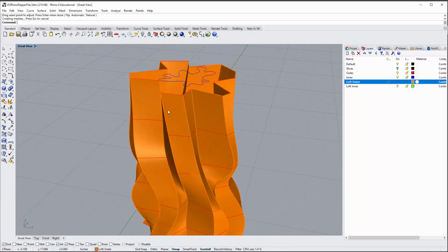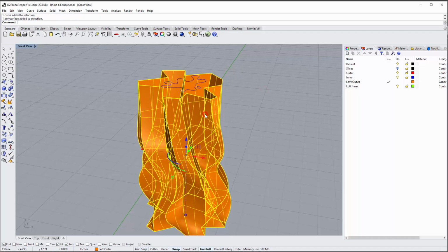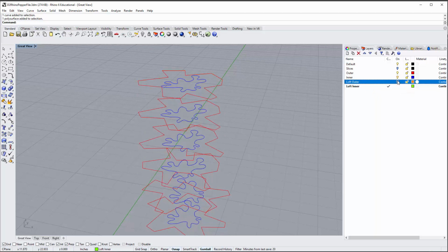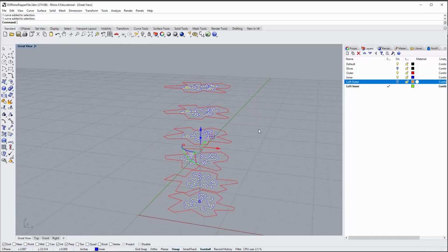All right. Now, you have to get used to switching between layers and turning things on and off if it's in the way, right? Now I want to do my inner curves, but this is kind of in the way. So what you can do is shift your active layer to the inner layer, right? And then use the layer visibility to turn off temporarily that orange layer, right? And that will allow me to select by holding down the shift key and clicking these in a sequence, right?